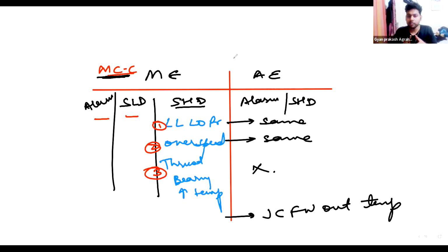What is the function of oil mist detector? Considering it is a bearing safety, if there is a hotspot generating in the crankcase because of bearing failure, that hotspot can cause an explosion because of mist generation. So you fit a sensor to find out how much mist is there in the oil.